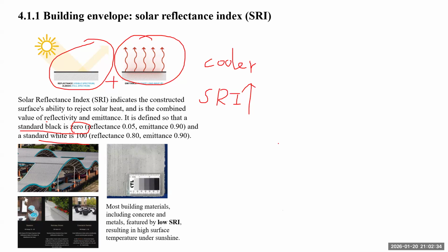Another story is metal. Metal is even worse. Why? Because metal has low absorbance of solar, but it has almost zero emissivity. All the heat it will trap. It doesn't know how to radiate heat into its surroundings. That's the feature of metal. Also, like when we're using silver, right? The low thermal emissivity keeps heat. So all metals have relatively low absorbance, higher reflectance, but really low emissivity.